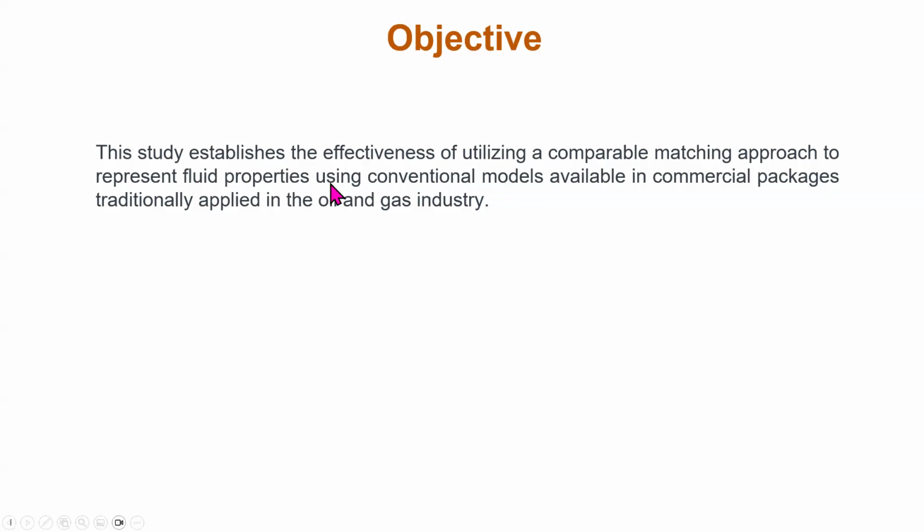We will use conventional models, conventional equations of state, SRK or Peng-Robinson equation of state, very traditional and standardized models available in any commercial package. So you can reproduce this workflow using WinProp from CMG. You can use PVTP from Petroleum Experts or PVTSim from SLB.